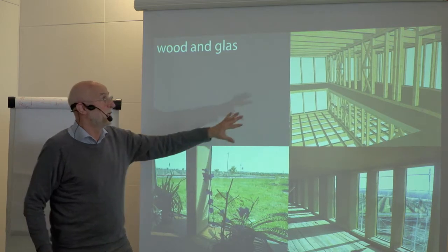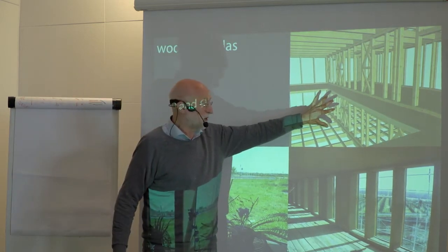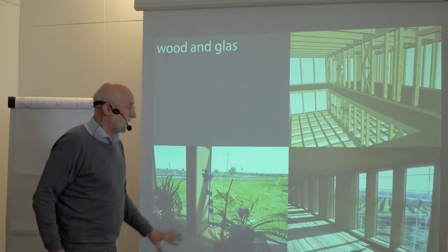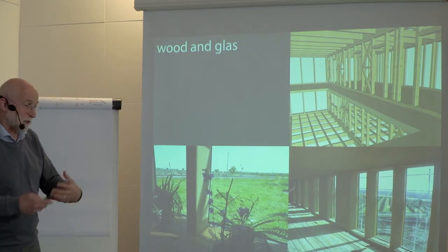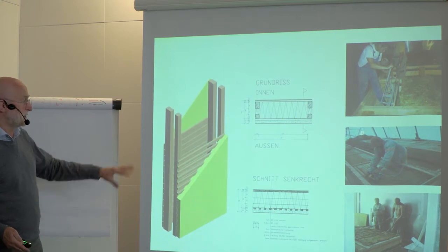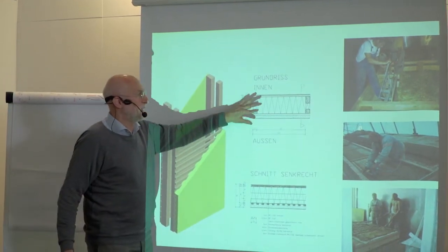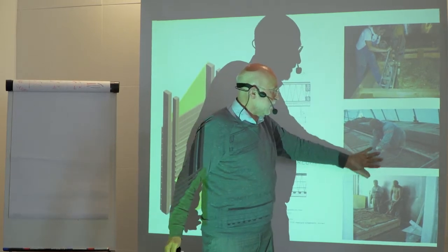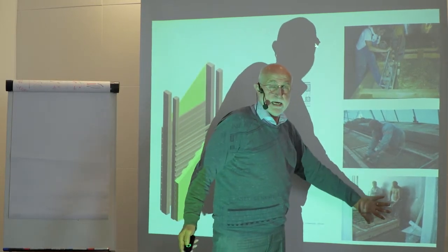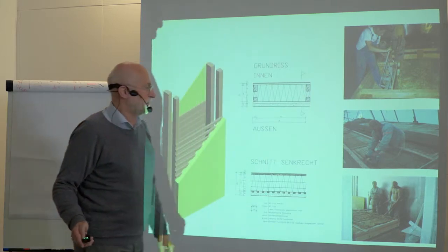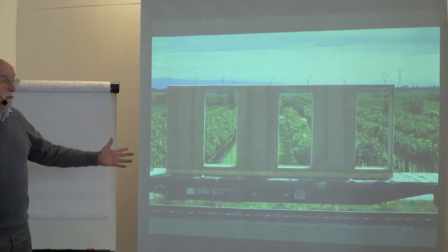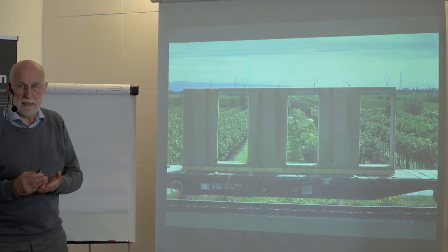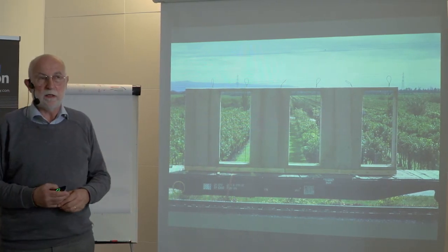And the third is wood for the construction, and very small glass and metallic parts for this building. So it's a completely clean building. It's a construction which is thermally separated: wooden piles, straw in it, clay on both sides, earth on both sides of this wall. The wall is prefabricated in the industry because you can work better in the industry.